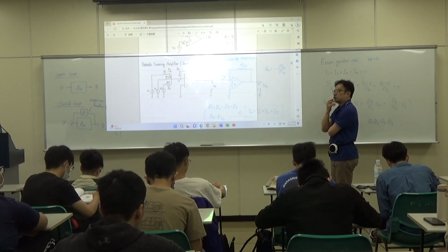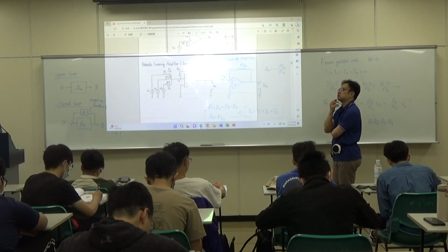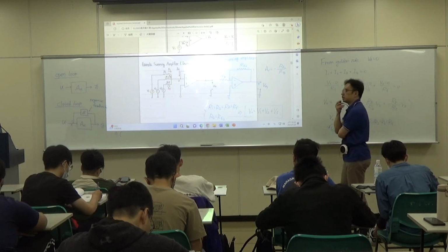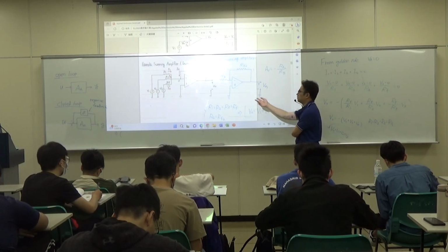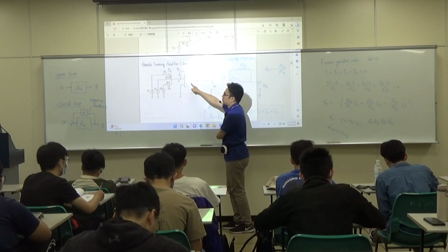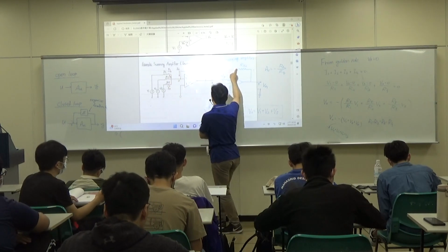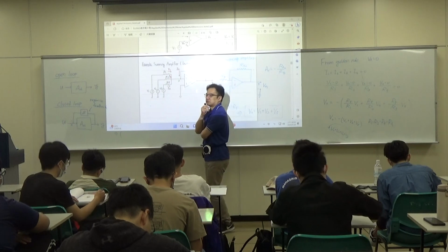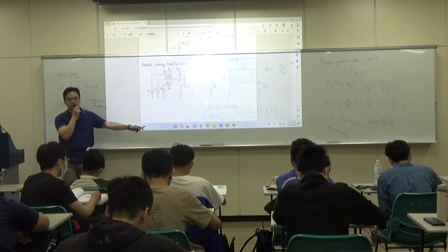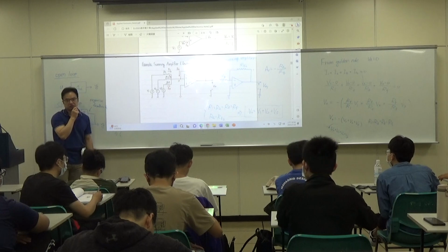This is what people do calculation before digital computing. Okay, so this is an old technique, but it is fast because you see you just need two operational amplifiers, and you don't need to do anything. You just need to pick the values of these resistances. Okay, so if your calculation is fixed, you can do this quickly and efficiently.